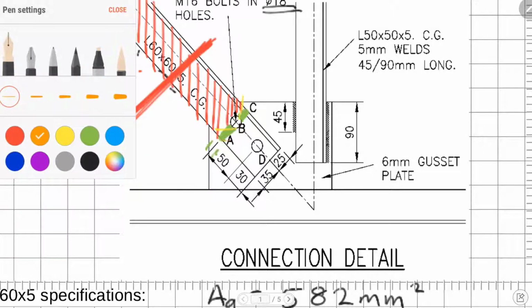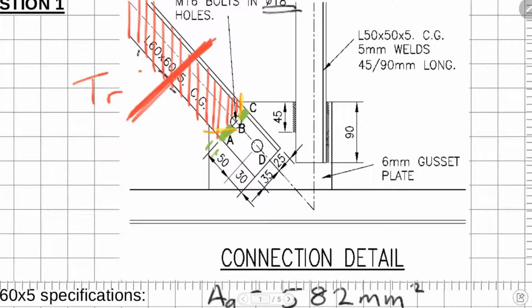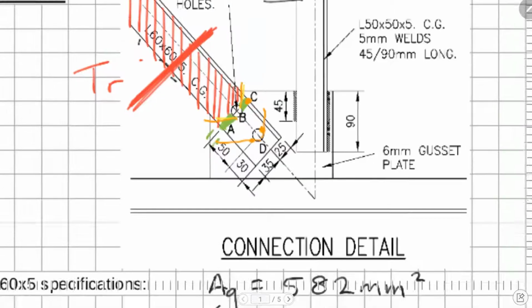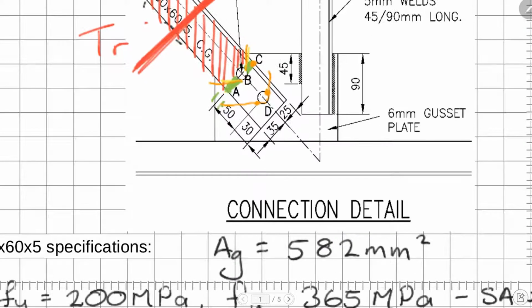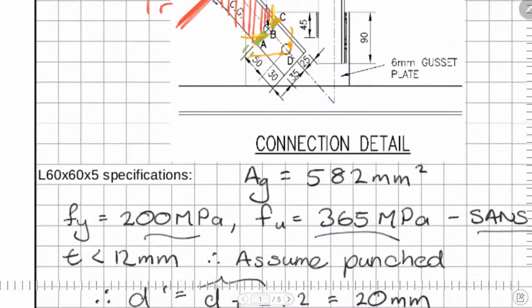So the stresses locally will be very high, and they will gradually distribute out through the section. But where it fails, especially the upstand flange, so the flange coming out of the page towards us, that is likely not to be fully efficient before it snaps. So first the bottom will break, and then that piece will break, and then gradually up the side. But the maximum stress is not going to be uniformly distributed.